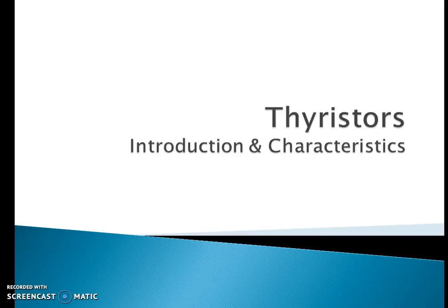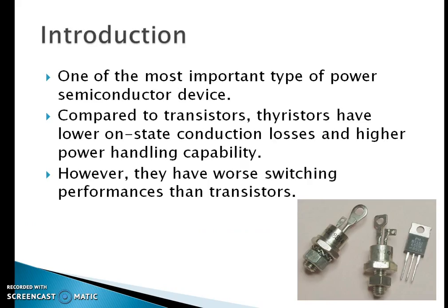Thyristor is basically a high power handling capacity device, which consists of a combination of two transistors having three terminals: anode, cathode and gate. It is a PNPN, that is 4-layer device having three junctions, J1, J2 and J3. There are several aspects about SCR, but it is mostly used in control circuits for handling higher capacity.